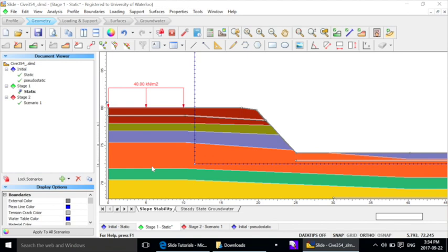And then, for sure, what is going to happen is that you guys have the first slope for the first stage. So you find the failure surface and you say, this is my factor of safety higher than 1.5 for static condition.